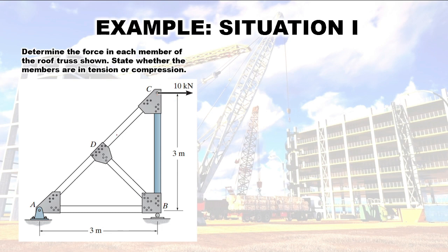Then this one, three members. This one, three members. Two are collinear members. So here, yung B natin forms three members, but wala tayong collinear member dito. No zero force members. So here at joint D, we have three members. You can see that AD and DC are collinear. Then at joint D, we don't have load. We also don't have reactions. Automatically, I can say that my force DB is equal to 0. So, mababawasan yung solution ko, correct? Now, after determining the zero force members, I can already solve for the reactions.